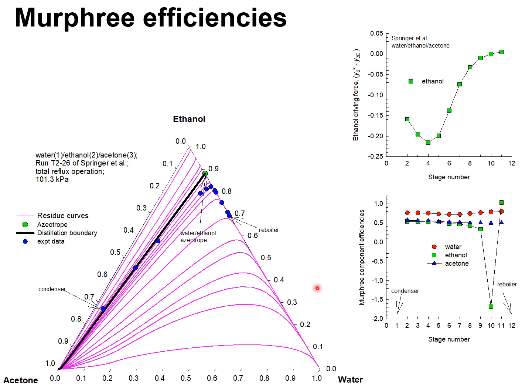But the more important task is to try to calculate the distillation trajectory, taking mass transfer effects into account, and using the Maxwell-Stefan model for the vapor phase and for the liquid phase, using all the details that were presented in the foregoing slides.